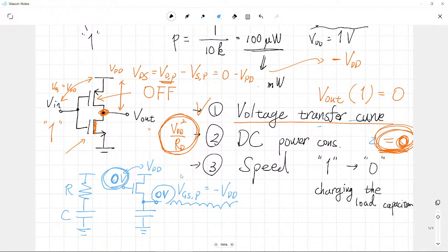You know that this maximum current will increase the charging speed quite a lot. So you can easily understand all of these conditions. When we need low conductance, the PMOSFET can contribute low conductance. When we need high conductance, the same PMOSFET can give us high conductance. That's the magic. A resistor has a fixed resistance value, so it cannot dynamically change its conductance.